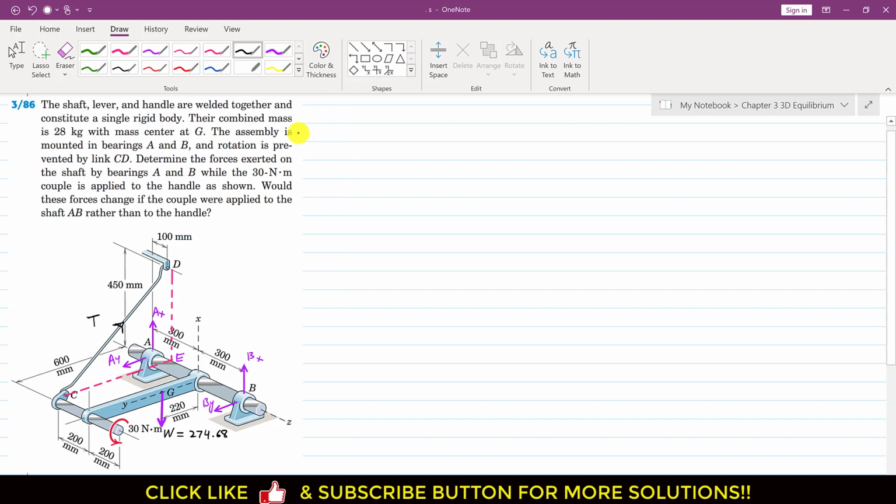Now first we will represent this T force as a vector, right? So we can write that this is T vector and this T vector will be equal to T magnitude into the unit vector, and the unit vector will be from C to B, and we can write that this will be T, and this unit vector will be CB vector divided by CB magnitude. And as we can see that this T force is two-dimensional, right? It has two components, right?